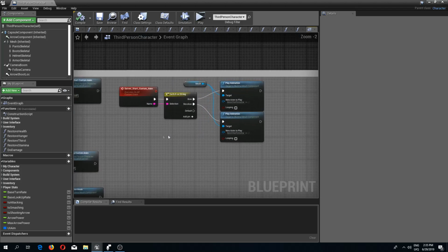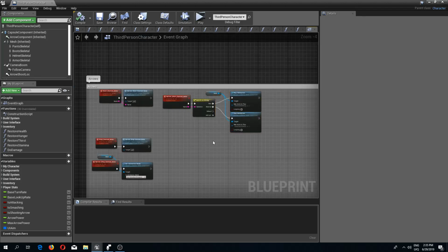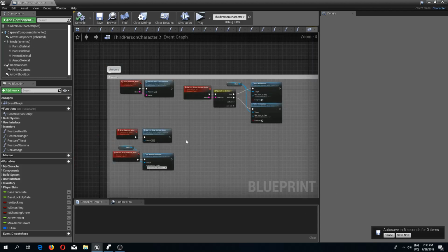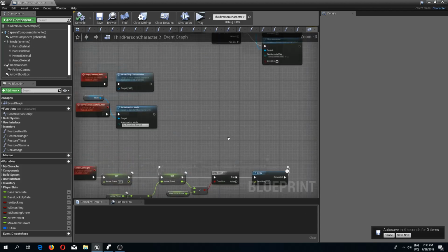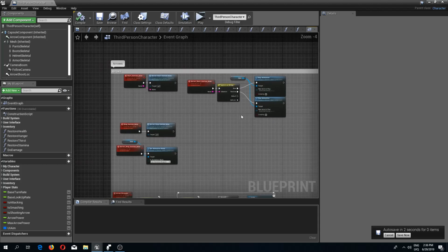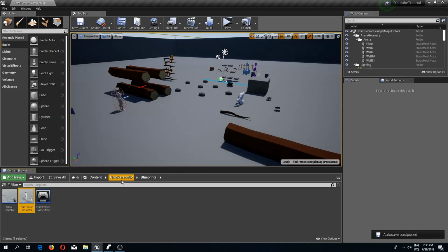So you can use this system like I used in here in case you want to create a specific animation for a specific movement. Let's say you want to do a hand gesture or head movement, just a custom animation. So you can use this system, but we are going to change this to the blend space animation blueprint.